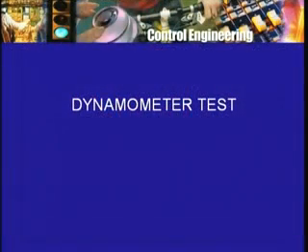The armature shaft has to be clamped, and then some force will be produced on it that will be counterbalanced by some other force which is measured, and so on. These are referred to as dynamometer tests, and some of you in your machines course may have done such tests. From such tests the value Kt can be obtained.